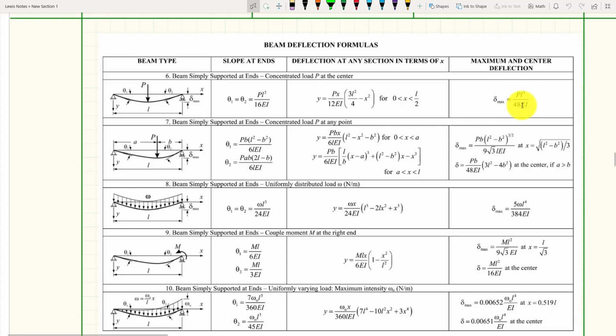Now what is the value for E? That is the modulus of elasticity. That's how rigid the material is. That's the slope on the stress strain diagram saying that this is a Hookean material. For aluminum, and you may want to check the lab sheets, it's typically around 10 to 11 mega PSI if you're in the inch system. If you're looking at steel, it's probably upwards of around 29 to 30 mega PSI. So we know that steel is going to be more rigid than aluminum.